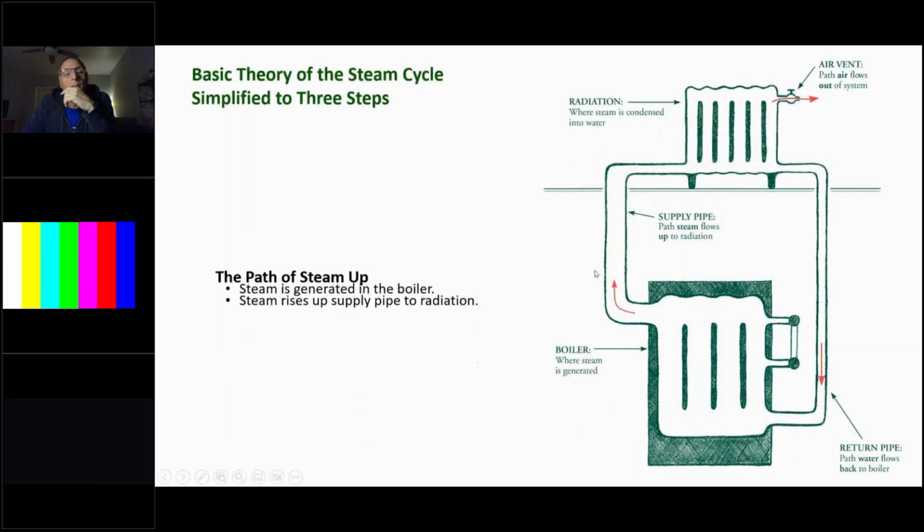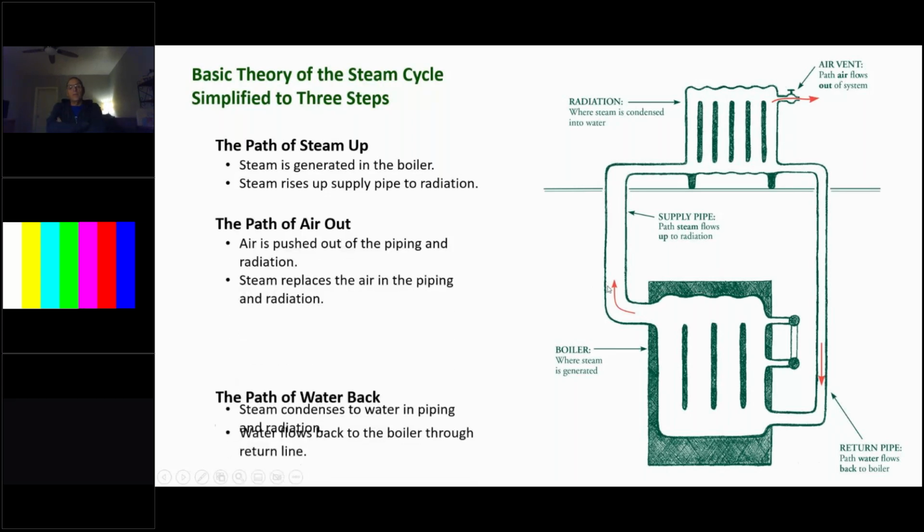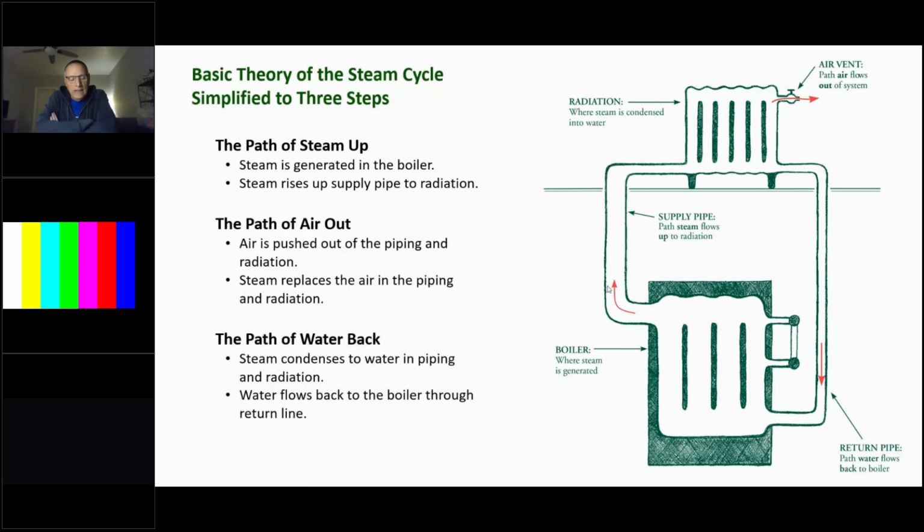If you see the water in that gauge glass start to bounce as it's going down, that means the water inside of that boiler is going to look like a wave pool up at your local water park. It is going to be rocking and rolling in there. And that's generally a sign of a dirty boiler also. If you've got a skim of oil on the top of the boiler, then it's not going to allow good steam to be produced. It'll kind of plop out.